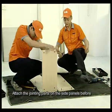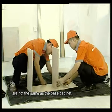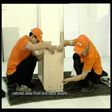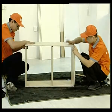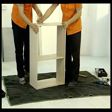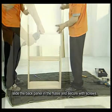Attach the jointing parts on the side panels before starting to assemble the cabinet body. Please note that the panel parts for the wall cabinet are not the same as the base cabinet, as the wall cabinet has a top panel, while the top of the base cabinet uses front and back levers. In the end, slide the back panel in the flutes and secure with screws.